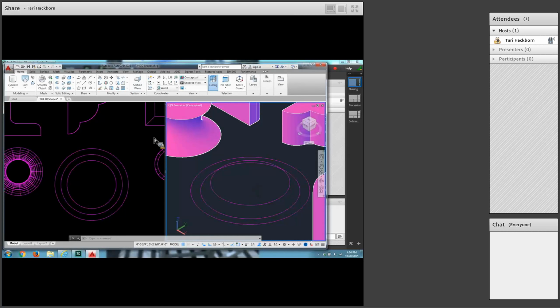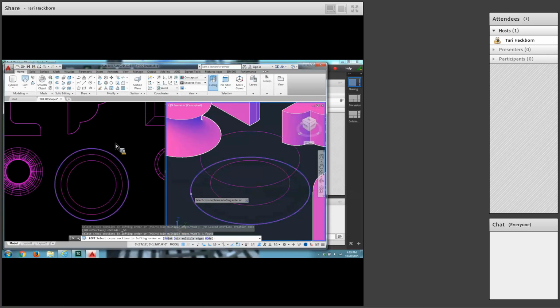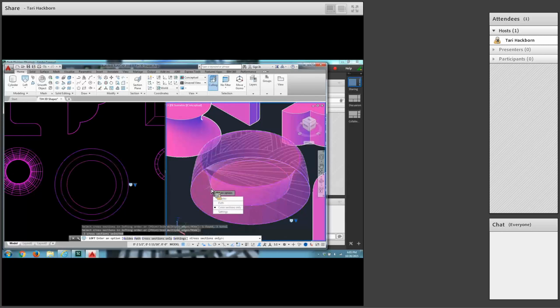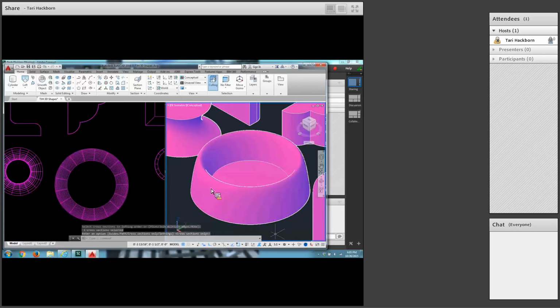That's this one, isn't it? Move. Select it. Enter. Grab a base point, which is the center, and type @0,0,0.5. All right, now here in the ISO view, with the loft command, select the bottom circle, the top circle, and then the middle circle. Is it going to let me? Yes. And enter twice, and you have a dog dish for Fido.